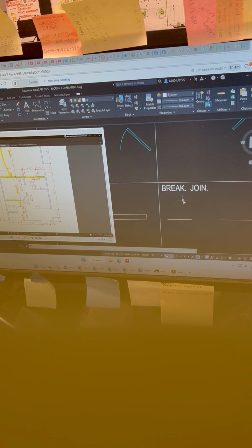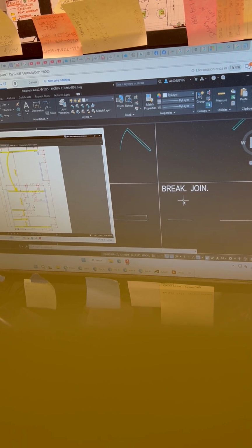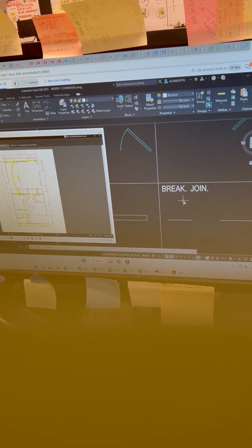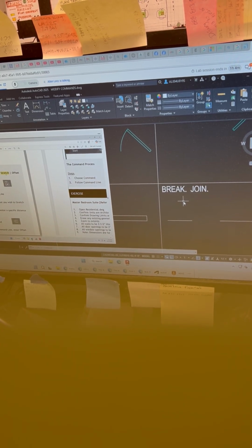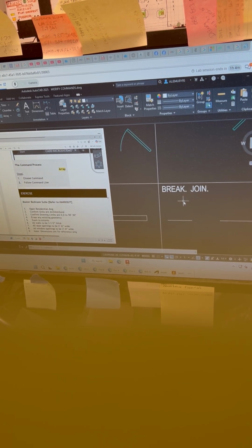So most of the time, what you're going to be doing when you're laying out entities for, particularly like I said, a floor plan, is using an offset command. So I want to spend some quality time on that particular command before we start to do this exercise. All right, with that in mind, I'm going to take a quick look at stretch and arrays. All right, so let's take a look at stretch.